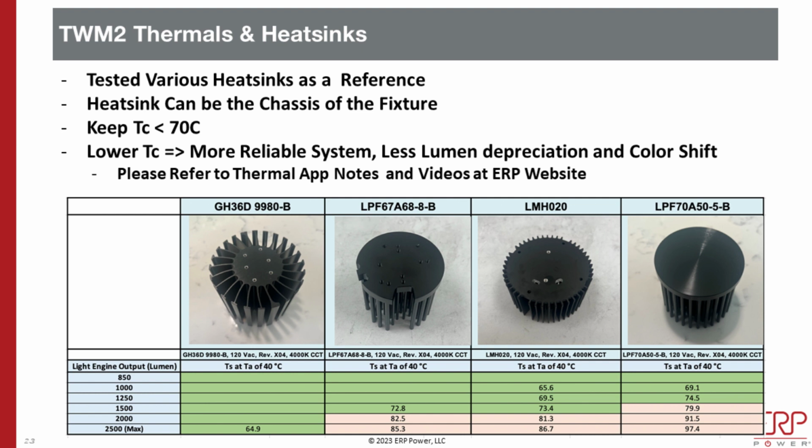Again, we're not a heat sink manufacturer or anything. So off the shelf, we just want to show you, as an example or as a reference, that you can use this and what kind of performance you'll get. Based on the thermal resistance of each of these heat sinks, you'll know what you have to do in a chassis if you plan to use the chassis or the fixture as your heat sink.